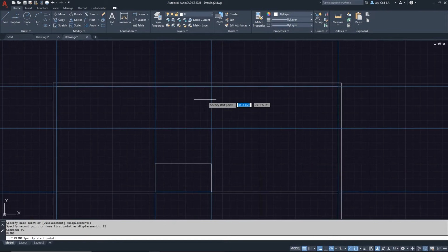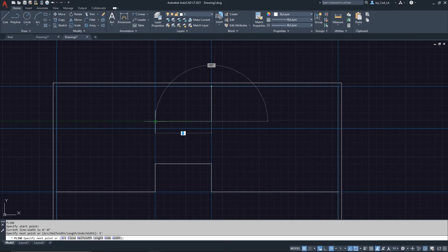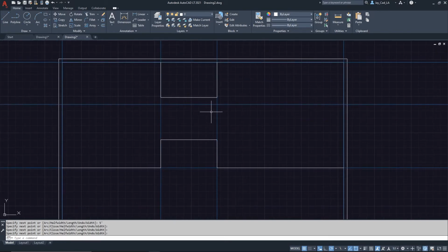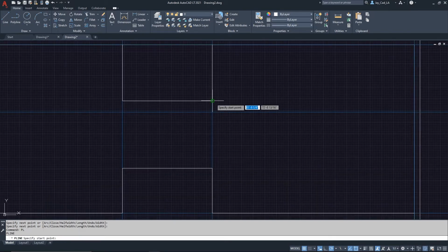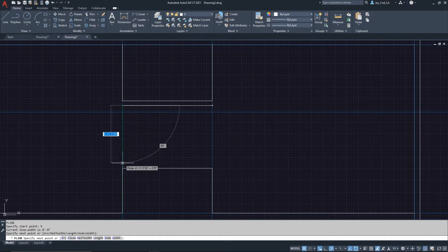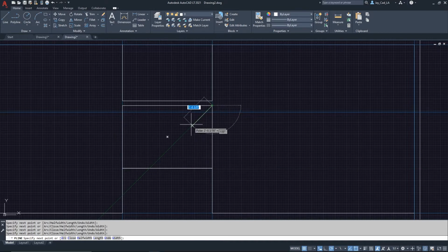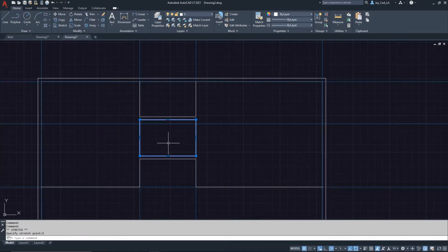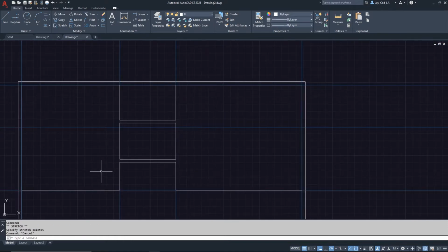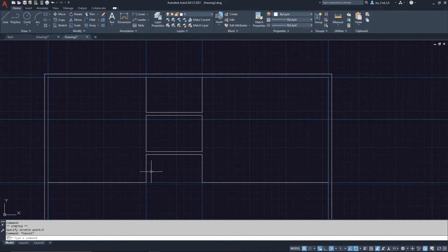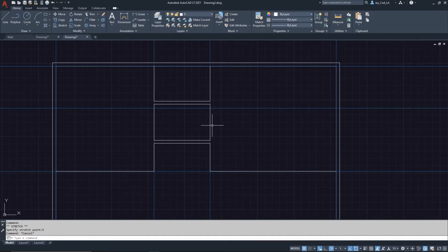Alright, then I'm gonna do a polyline. I'm gonna come down here by, let's do 5 feet. Then here and here. And then I'm gonna basically draw another polyline on the other side, right here. And then up to here, here, and here. And I'll click enter. And then this one, I'll just push it 5 inches upwards just to indicate the interior, the wall thickness over here. Right, so we have all of this so far.